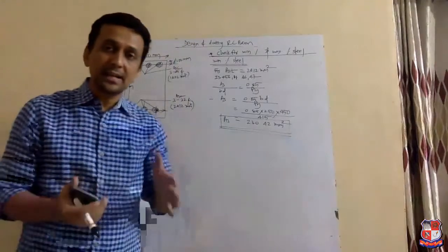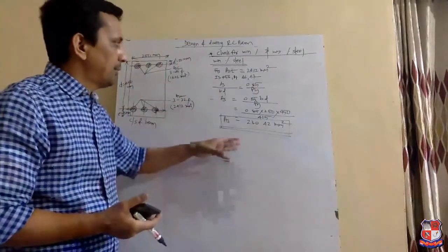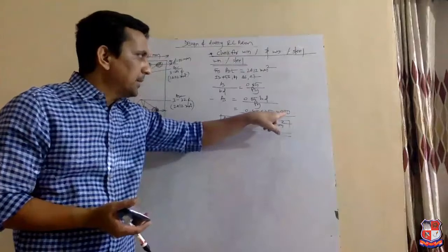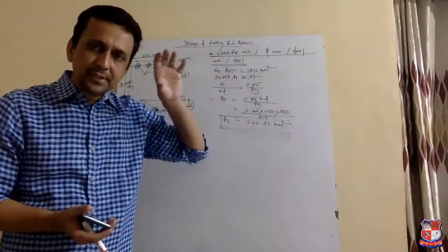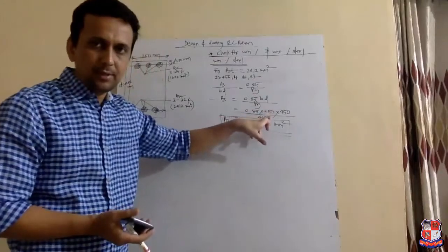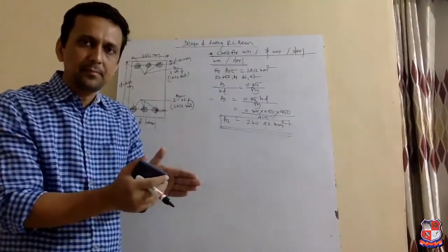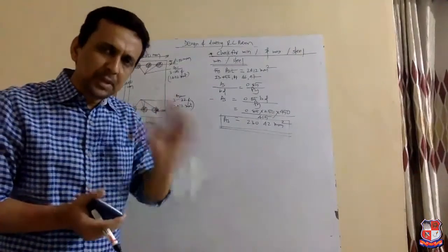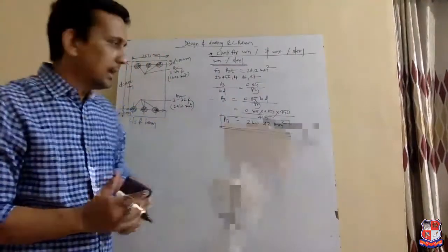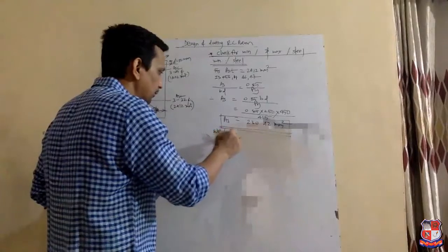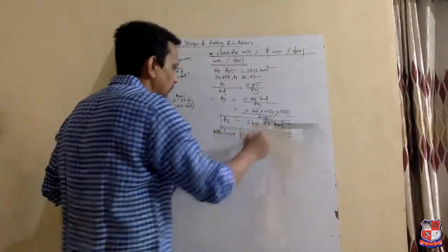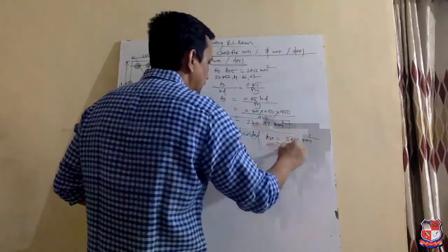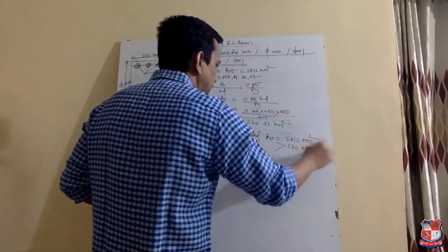230.42 means what IS has recommended. If the width of the beam is 250 mm, the effective depth of the beam is 450 mm, and the steel grade used is 415, then in that beam the minimum area of reinforcement must be 230 mm square, and we have provided AST equal to 2412 mm square, which is greater than 230.